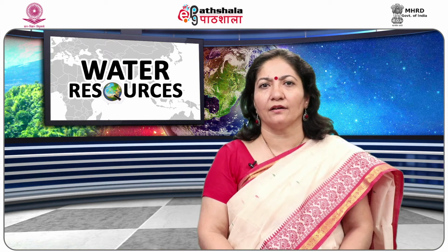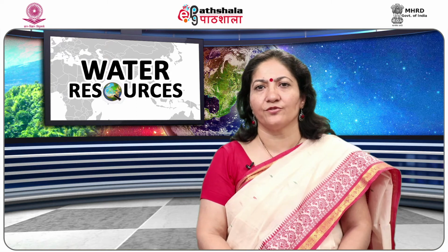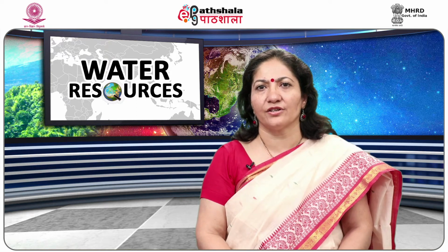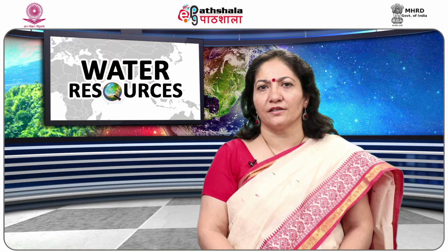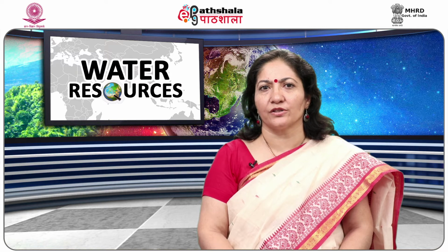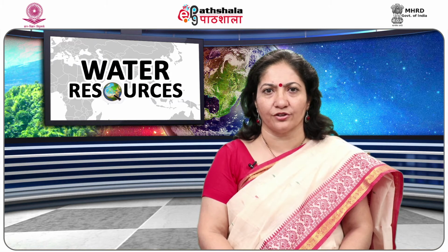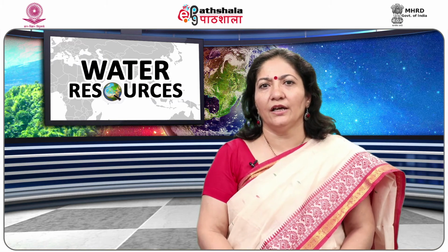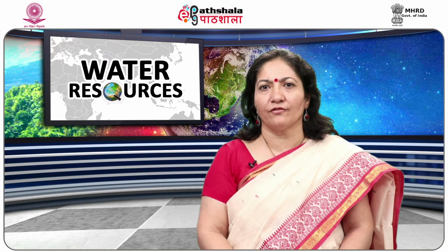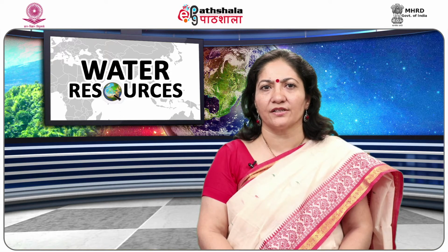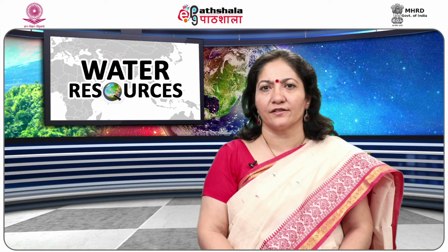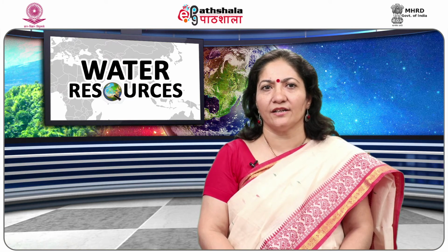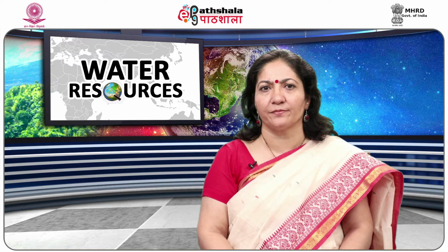The highly cemented sedimentary rocks have a lower porosity, as shown in figure 7, as compared to the uncemented void spaces. In carbonate sedimentary rocks such as limestone, groundwater occurs in fractures and cavities formed as a result of the dissolution of the sediments. This is shown in figure number 8, which shows the solution increases the porosity of the rocks. In igneous and metamorphic rocks, which are very dense crystalline rocks, porosity is controlled by cracks, fractures and faults. Structure of the rocks and its weathering are also important factors. Porosity is low as the minerals tend to be intergrown, leaving little void space.